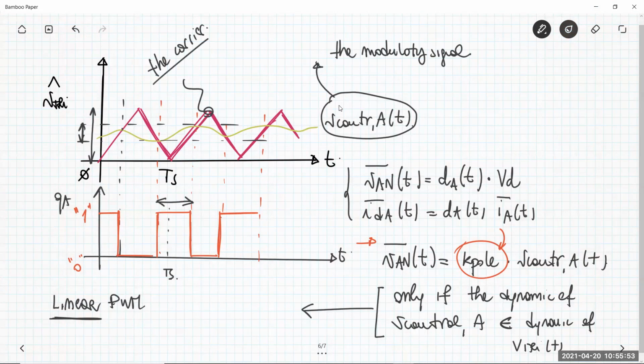So sometimes you can see, with the classic standard terminology of the telecommunication field, that the control voltage is a modulating signal, and you have a carrier. So you can transfer this information into another quantity. In this case, it is the width of these pulses, the variation of the duty cycle, and then you can amplify, etc., and demodulate.